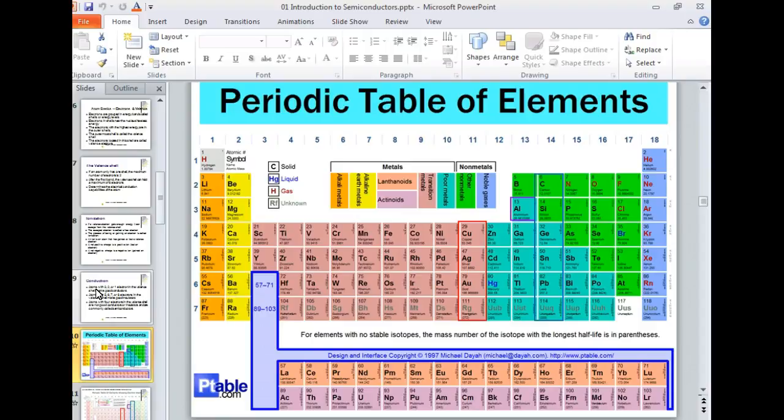So up there, when it comes from your house, the downdrop from the house is probably aluminum. You took all that tape off of that splice up there, you see it looks like grease, just like grease all over there to keep the what? Keep the oxidation away from the aluminum and the copper.